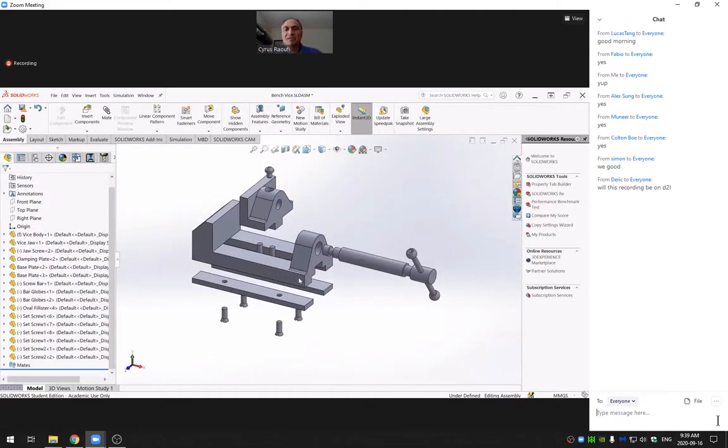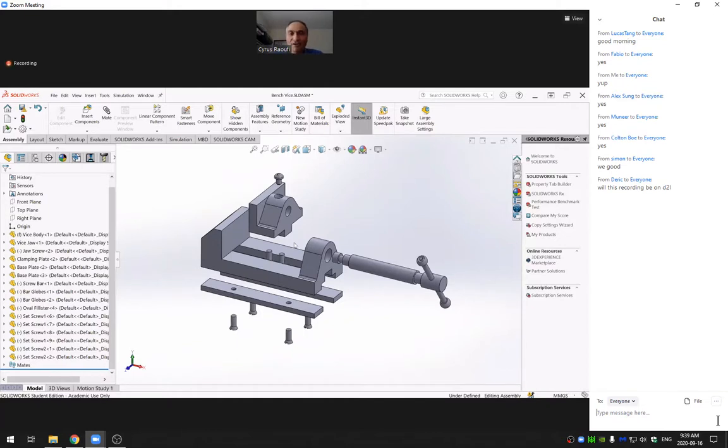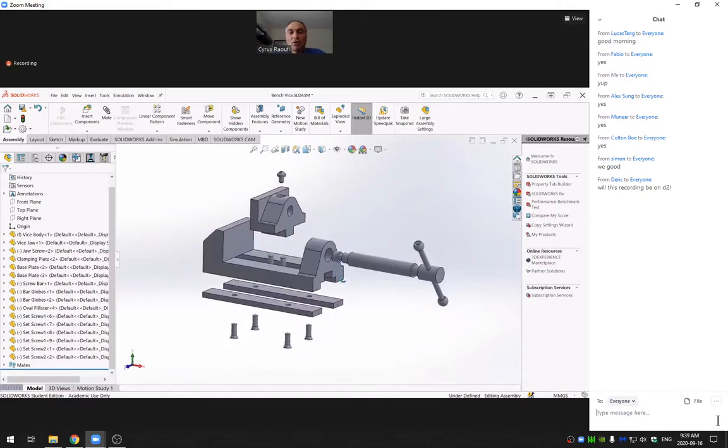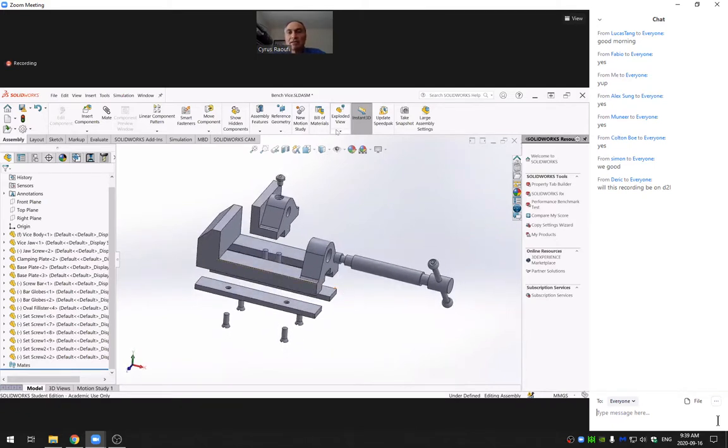As you see, it's a little bit art. It depends on you, and you have to spend time in order to create a neat exploded view, something that is clear in terms of the orientation and position. Also, as I said, you can add explode line sketch to show the way that the people are going to put the parts together.